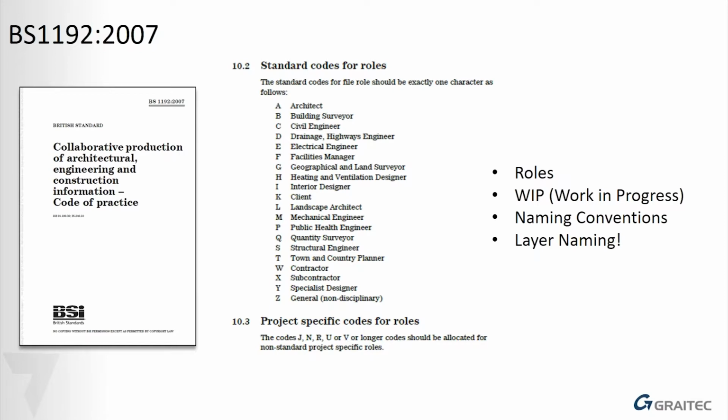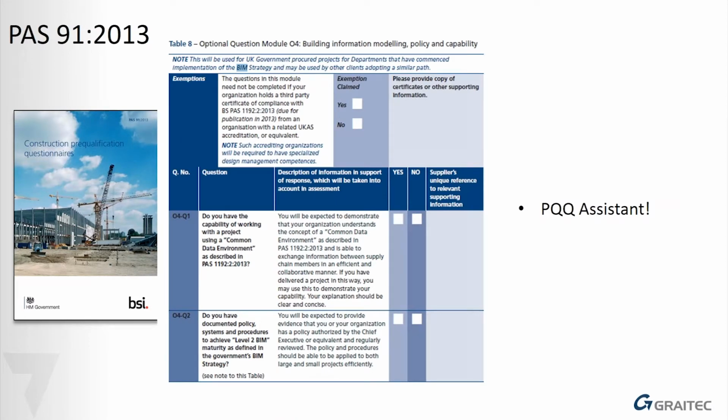So whether that was OpenOffice or Microsoft Excel, as long as it could read an Excel file, that was the minimum software requirement for BIM level 2. And that's where the COBie document, this COBie standard, came in, so that everyone was capable of producing a BIM level 2 piece of information.